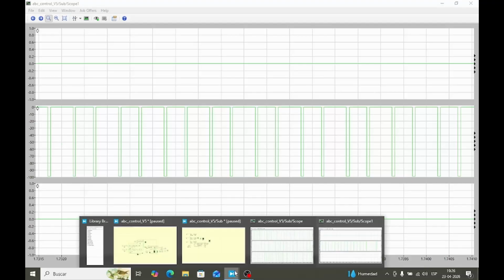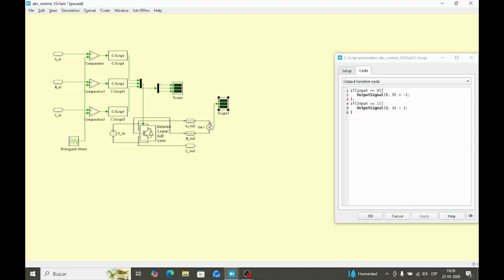At the output is the PMSM, as I said before, and since it has inductors, it will filter the signals that are coming for each phase, like a low-pass filter. So it will integrate this rectangular wave, and it will grow a little, grow a little, grow a little, with some harmonics, but not so much in this simulation. These are the control signals and actuating signals that go to the motor itself.